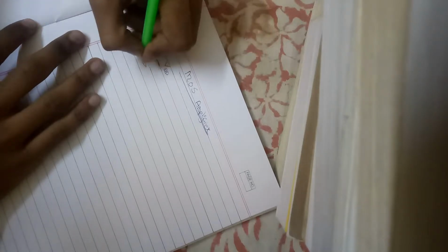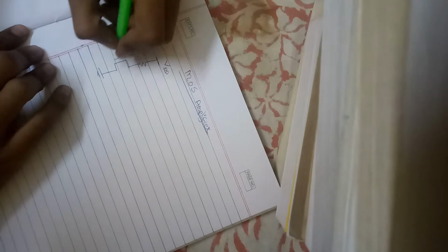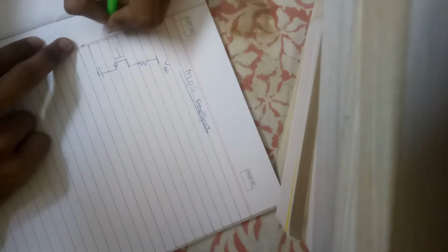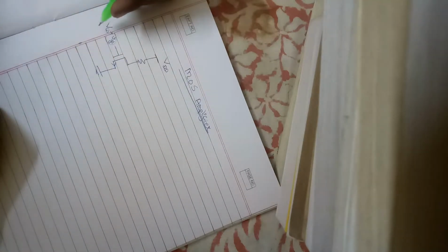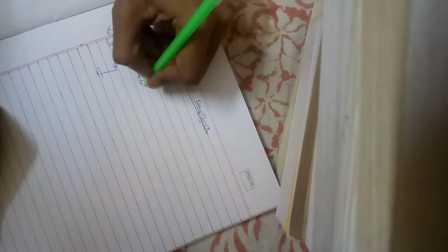The basic diagram is that first we have to give a voltage source and a MOSFET like this. We have to connect it like this, and here we have to provide first of all a bias voltage, and we also have to provide the voltage that we need to be amplified, that is an AC voltage, because the DC voltage cannot be amplified like that. So this is the first requirement, and we have to take the output from here.